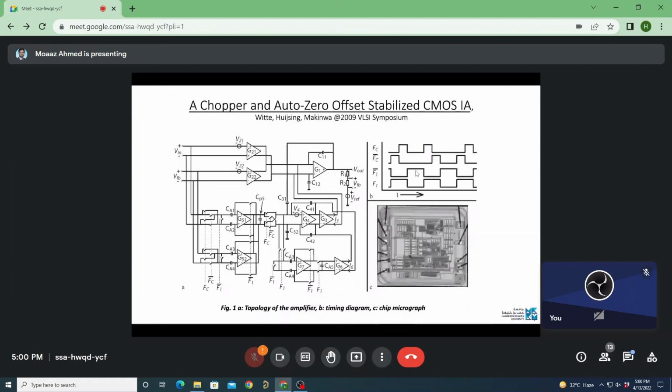Anyways, can you guys see this? It looks very daunting, very complex, but it is not. It's very simple. It's a set of transconductors only. There are two paths. One at the top, you see G21 and G22, followed by an output stage G1. These G1, G2, G21 are all transconductors. Very simple. You would have done telescopic stages or folded cascode stages, and I'll show you a transistor level implementation also at the end, one of my designs.